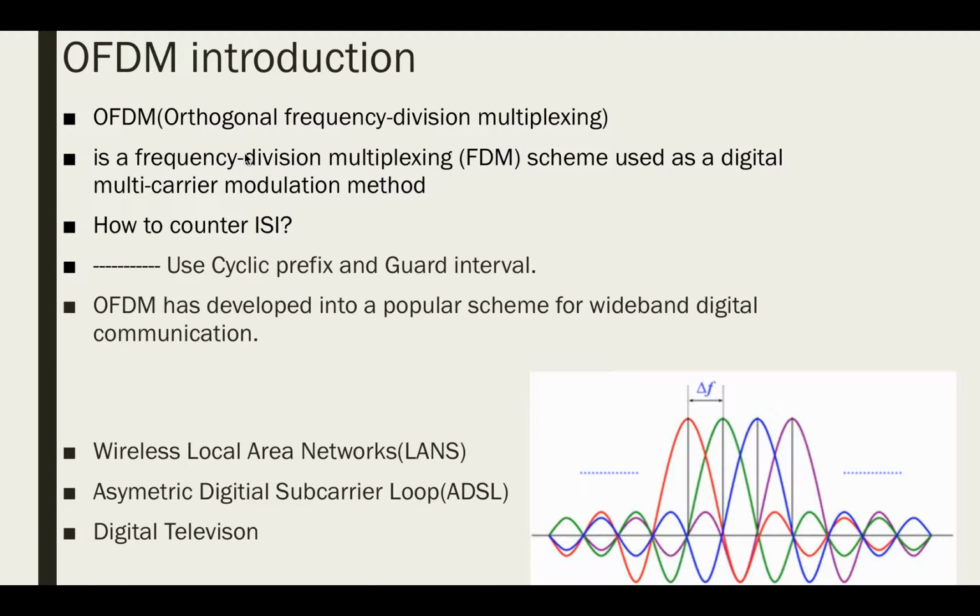Here's the introduction of OFDM. OFDM stands for orthogonal frequency division multiplexing. It's very similar to frequency division multiplexing, FDM, a technology which has been widely applied. Like the basic principle of FDM, OFDM converts the high-speed data stream through serial and parallel conversion, then assigns it to a number of subchannels whose frequency is relatively low for transmission. The difference is OFDM technology makes better use of orthogonality to improve the spectral utilization.